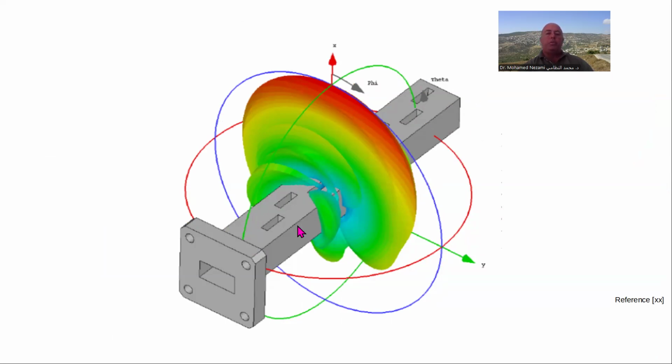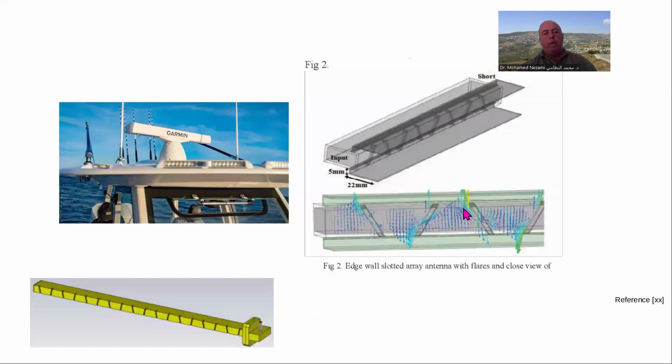Now, when you draw this in HFSS, make sure you put the center of the HFSS constructed model right at the center of the waveguide, so that you can see the pattern is centered correctly. Otherwise, you end up with a geometry here, and the radiation pattern will be offset from the center, wherever that happens to be.